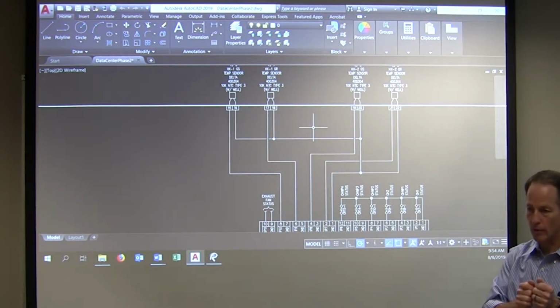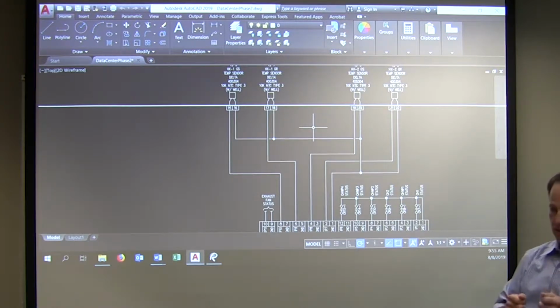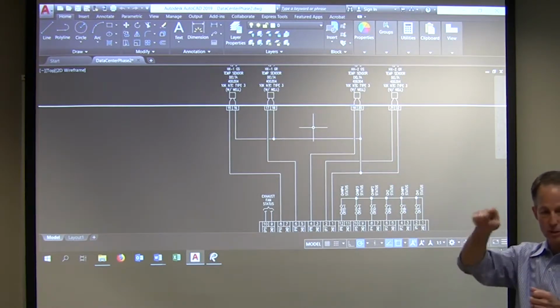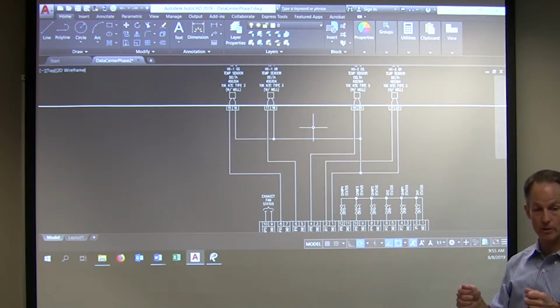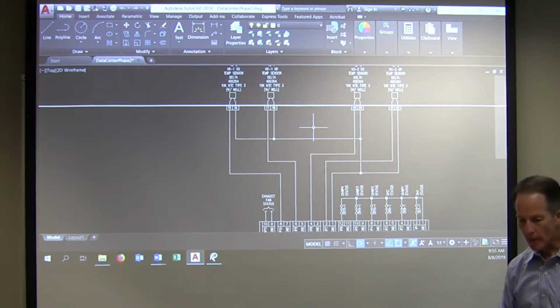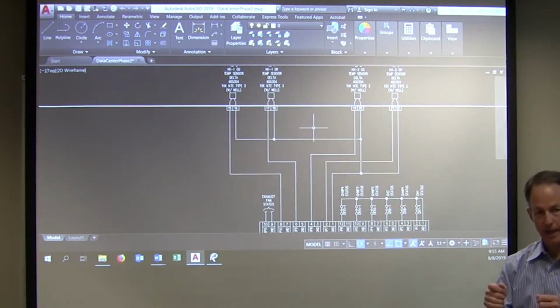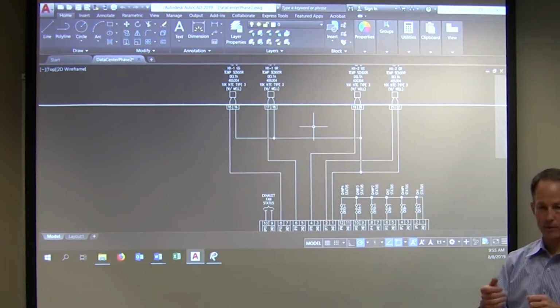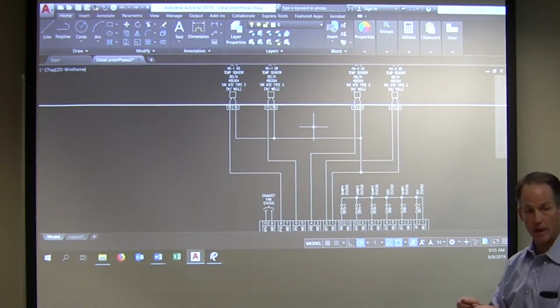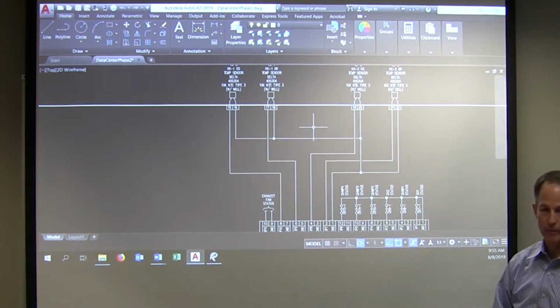So what also should we do as we're reading it? Try at least one of the legs to ground, because if you do at least one, you're going to see the resistance of the original. But I should see how much resistance? You should be open, right? It should be like infinite, or it should say OL. And if it doesn't say OL, if I'm reading 10K or 11K, then we know that there's some. So I check the other lead, and then maybe I've got the ground on the other wire. Okay. All right.